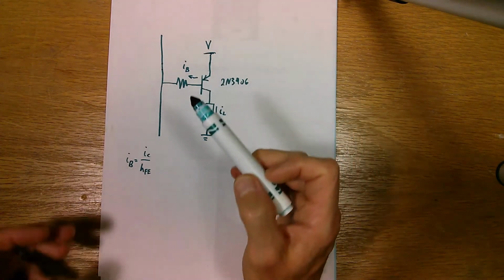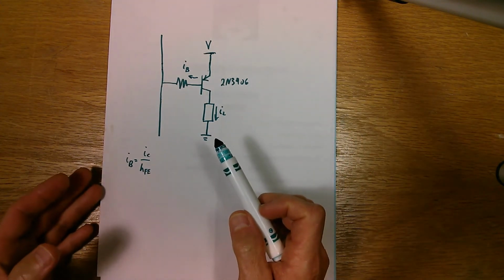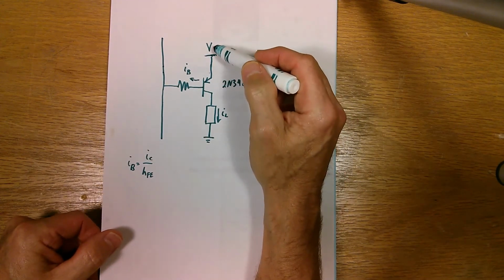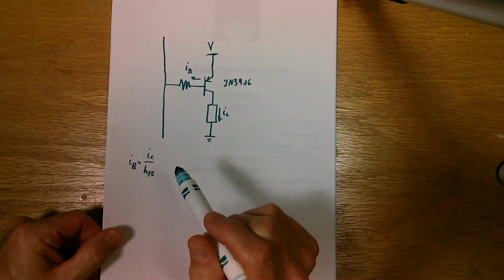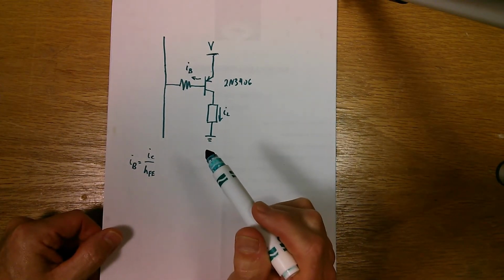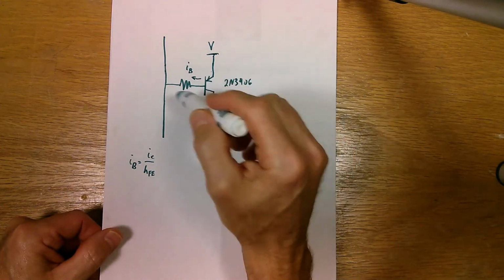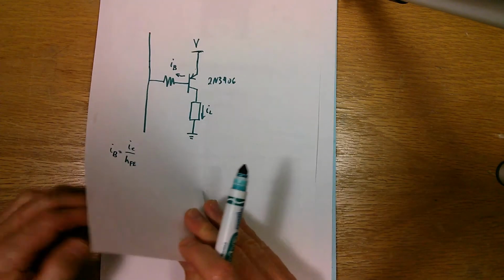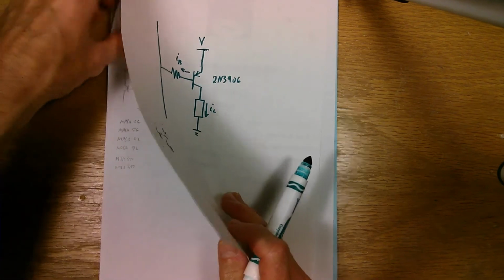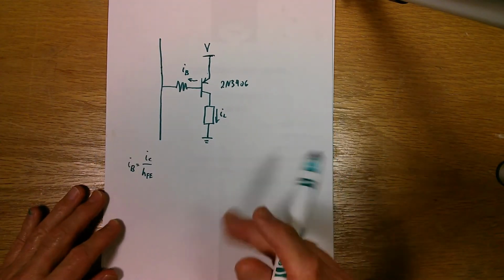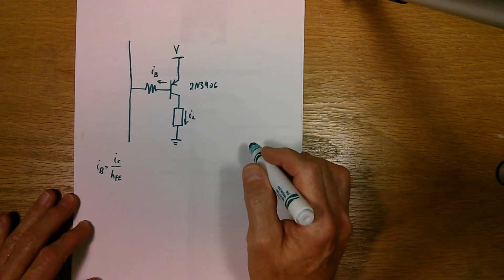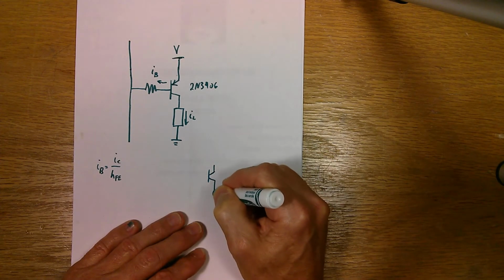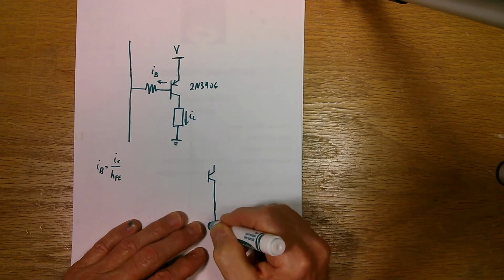If I want to switch a load with a PNP transistor with a higher voltage, I need to use two transistors, and the two transistors will do something that we call level shifting. So, whoops, I'm running out of blank paper here. I'll just draw it underneath. We will keep our PNP where it is in the circuit, and our load is down here.